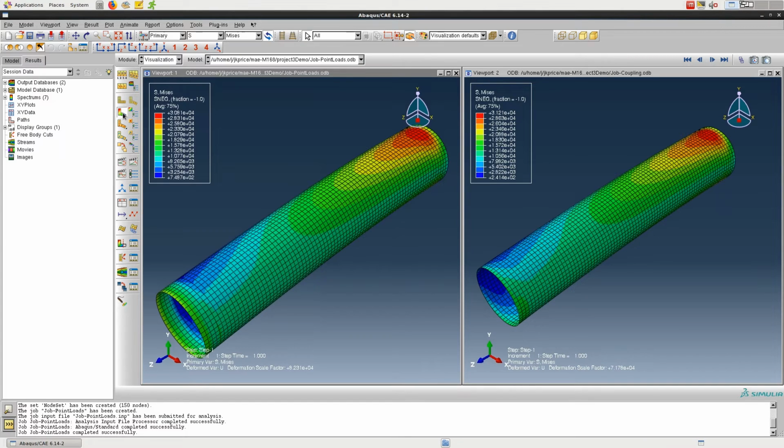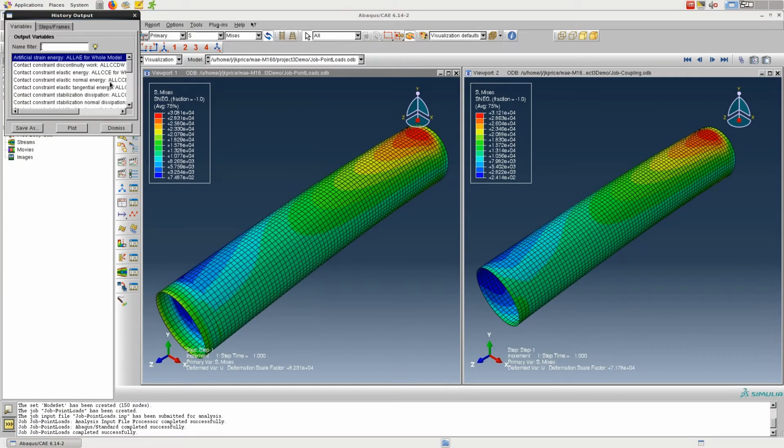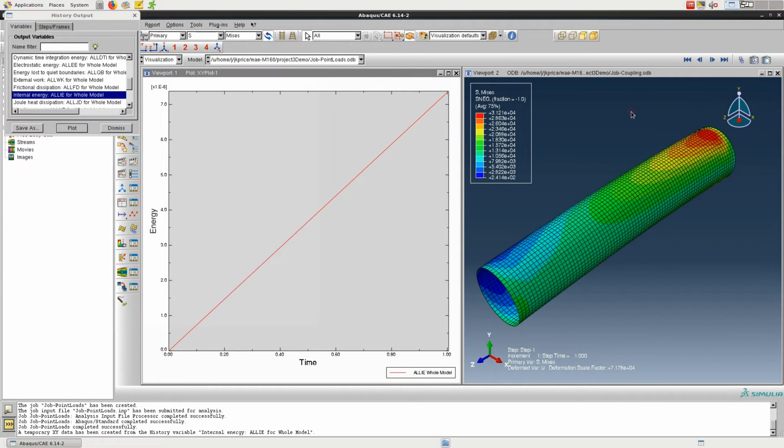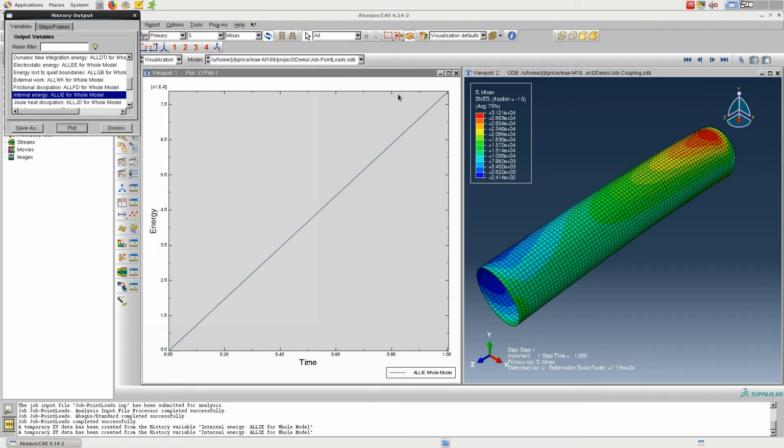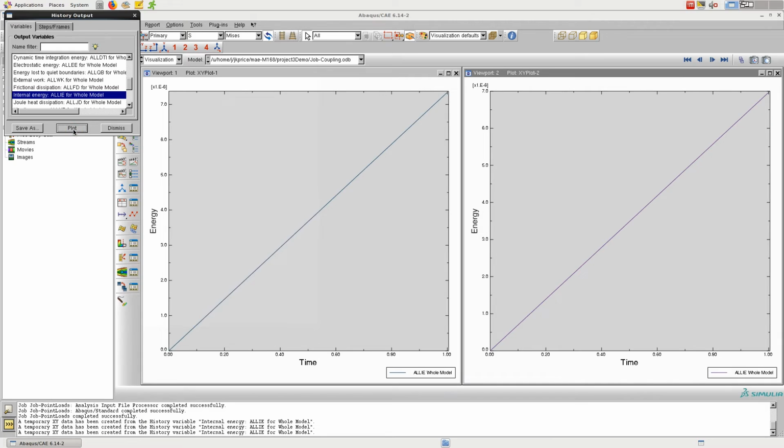The stress distributions for both methods are similar, but the one where we apply the point forces has a bit of strange behavior towards the edge. And the strain energies between these two methods are pretty much the same, but again, the distributing coupling is likely the better option due to the more fluid stress distribution near to the edge.